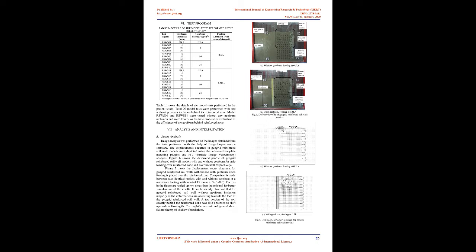Properties, values. Sand. Specific gravity, G, 2.61. Soil classification, USCS, SM. Coefficient of curvature, CC, 1.17. Coefficient of uniformity, CU, 1.99. Maximum void ratio, 0.943. Minimum void ratio, 0.691. Unit weight of soil at 55% relative density, kg/m3, 1446.7. Unit weight of soil at 85% relative density, kg/m3, 1510.41. Angle of internal friction at 55% relative density, 32.